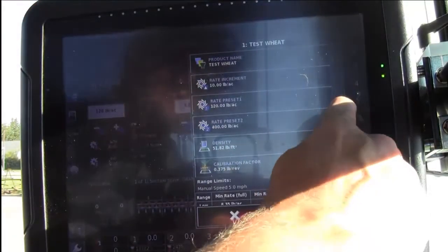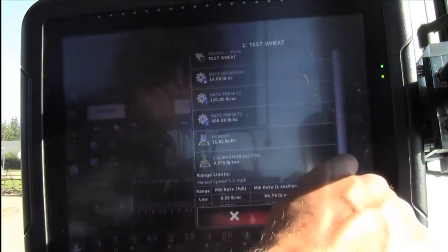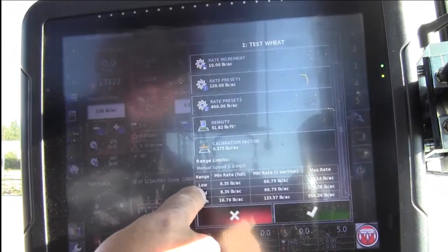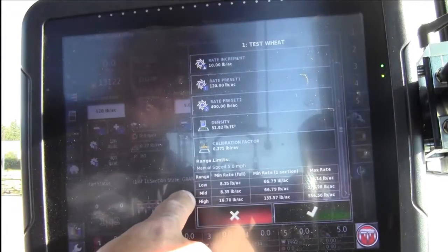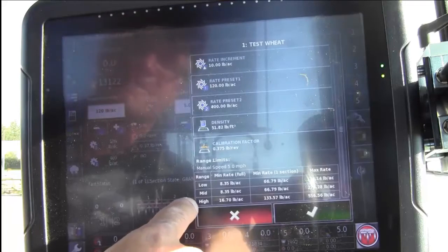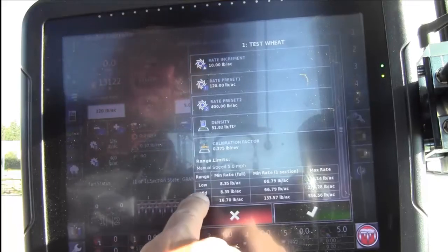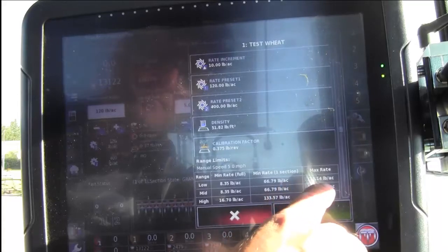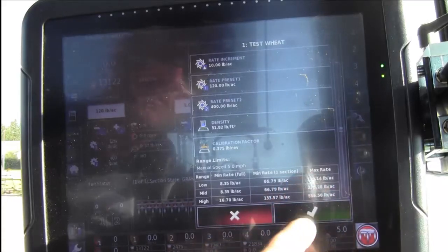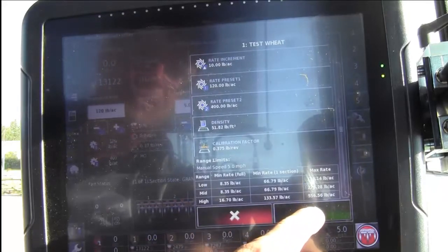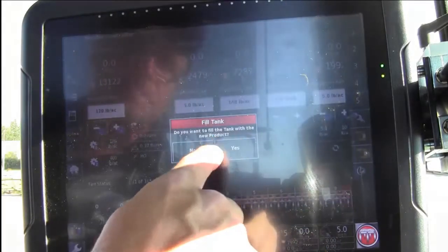If we drag the slide bar on the right hand side down to the bottom, now we can view the ranges. Each of the metering augers on the tank has 3 ranges, a low, mid, and high. For our functional test, we want to test the upper limits of the system, so we'll probably want to be in low for all of our different settings so we can test the upper limits of the rates. Okay, note that for future reference.